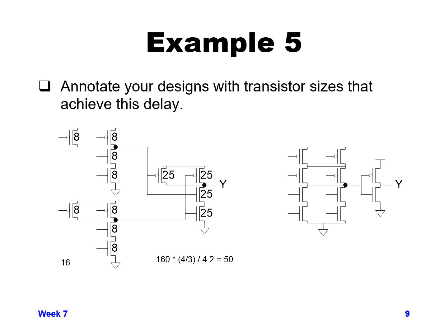Then we just need to calculate the size of the transistors for the final output NAND gate. If we go back to the previous week's lectures, when we were looking at sizing, we take our output capacitance that we need to drive. The output capacitance was given as a value of 160.